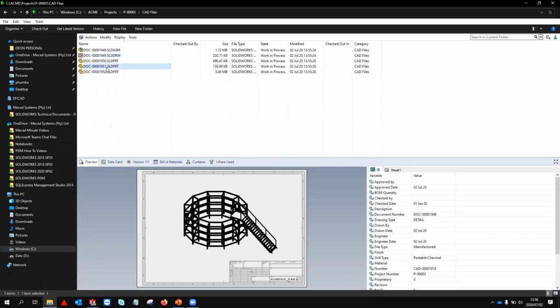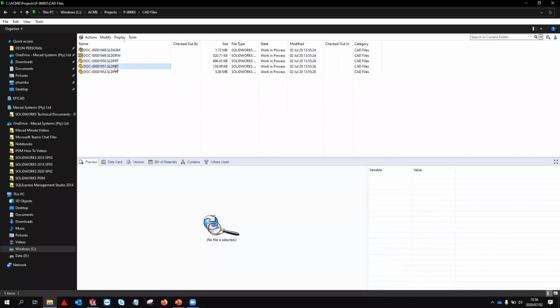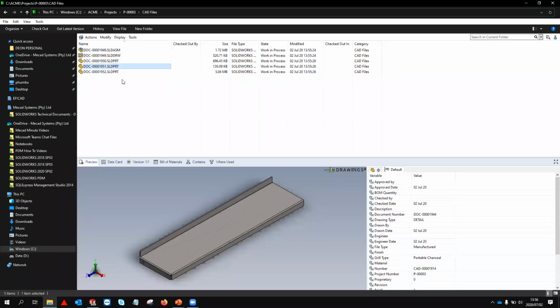But for example, this stair file, this will be a standard component. It will also be referenced in other new assemblies that we create. Now, when we move those new assemblies then from our sandbox folder into a project folder, we are therefore going to create duplicates of the staircase file. Now, the nice thing with SolidWorks PDM is the first time that a file is shared between multiple projects, you can simply take that file.